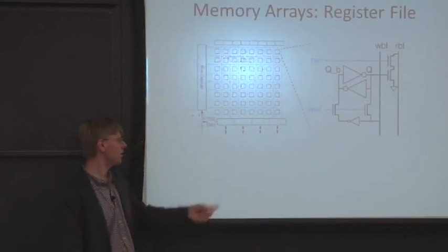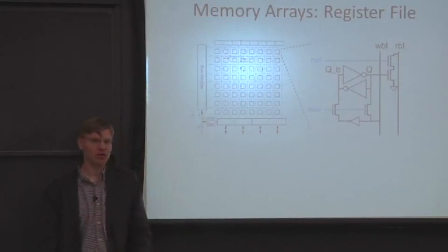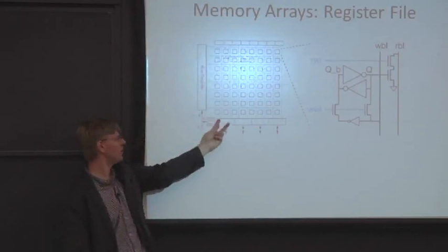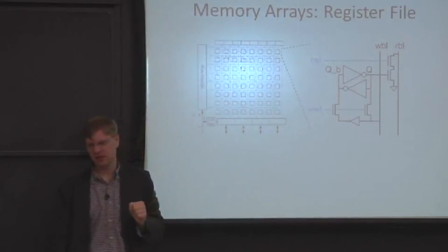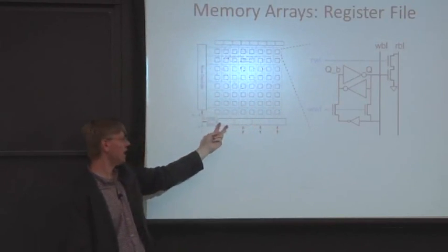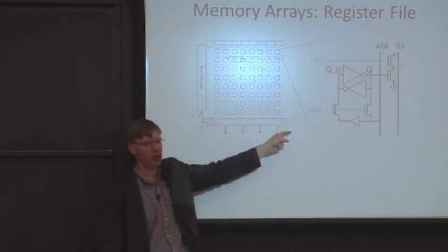So in this diagram, we have a 4-bit wide readout or write, and we're going to have 1, 2, 3, 4, 5, 6, 7, 8 bits across here. So we're going to need a 2-to-1 column decode. So this is a 1-bit decode here.